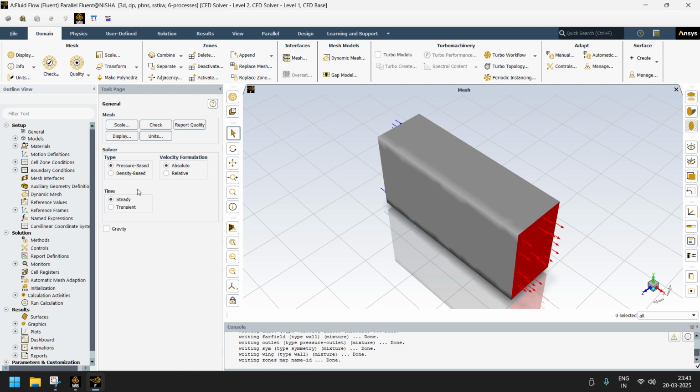It will be maybe 40 meters per second I am going to take. So flow can be assumed as incompressible, so you can go for the pressure based. And now I have taken just 0 degree only. Up to 5 degrees at least I can consider it as steady flow. Maybe after 5 degrees I have to go for a transient, different study. So I am choosing pressure based due to incompressible flow, and low angle of attack, I am choosing steady only.